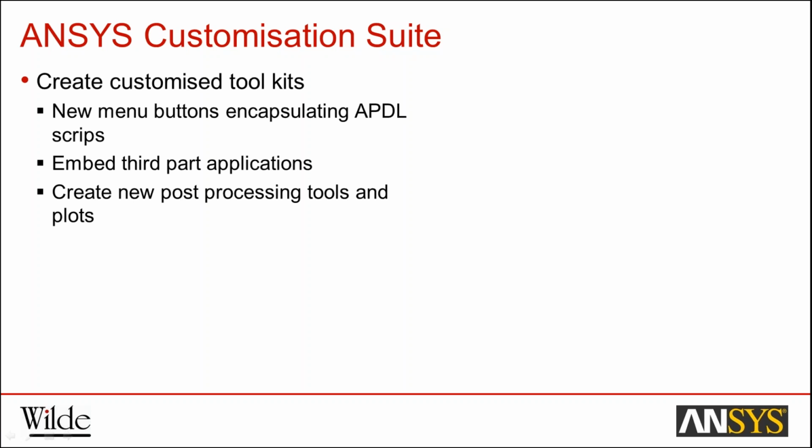Yeah, the ANSYS customization suite, what they say, customized toolbars and toolkits. So if you were to create a customized button on your screen, for example, to execute some commands or something like that, you can do that with this ANSYS customization suite. We can also use it to, for example, encapsulate APDL command snippets, embed third-party applications or communicate with third-party applications, something like Excel or MATLAB maybe. We can also use it to create new post-processing tools, so if there's some additional results that we want to plot, we can use this customization suite now to create these ACT extensions to do this.